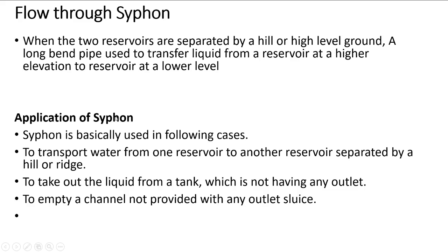So what are the applications of siphon? Siphon is basically used in the following cases. First, to transport the water from one reservoir to another reservoir separated by a hill or a ridge. Second, to take out the liquid from a tank which does not have any outlet. And third, to empty a channel not provided with any outlet sluice.